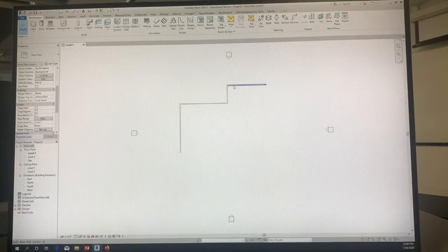And then here's the beauty. When I create the new construction, it will remove all of those items that are demolished. So all that's left is the as-built that I specify is staying. Okay? So this phasing of drawings is a really nice way of being able to organize all your information. As-built, demolished, and new construction in one file. Okay? So that's why I wanted to show you this. Next week's class is all about phasing. Okay? So we're going to do that next week. So I want you to prepare your as-built so we're ready to do the demolition and the new construction drawings next week. Any questions?